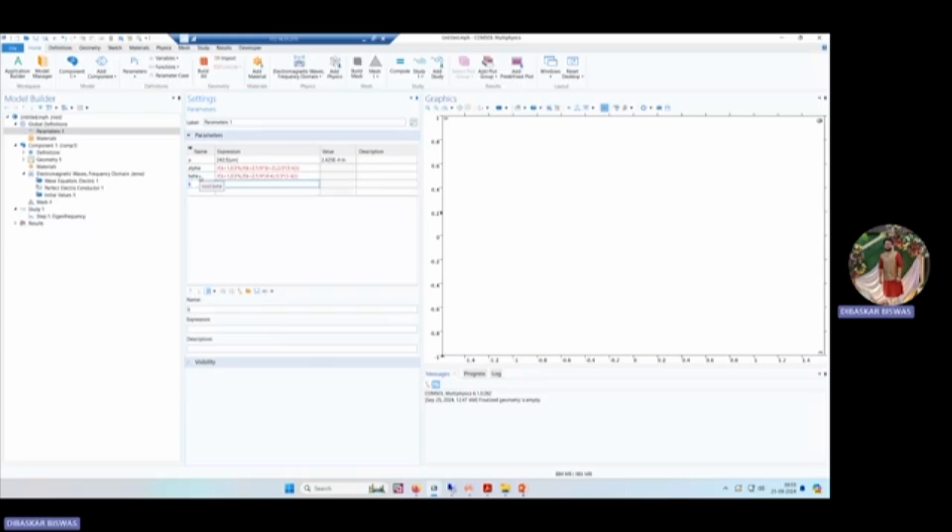You just give any arbitrary value, 0.1. So now see the red color on the statement, the red statement has actually turned black. So it means that we removed that error. Okay, then you need to define k naught here. So it is 4 into pi divided by, first bracket, square root of 3 into a.